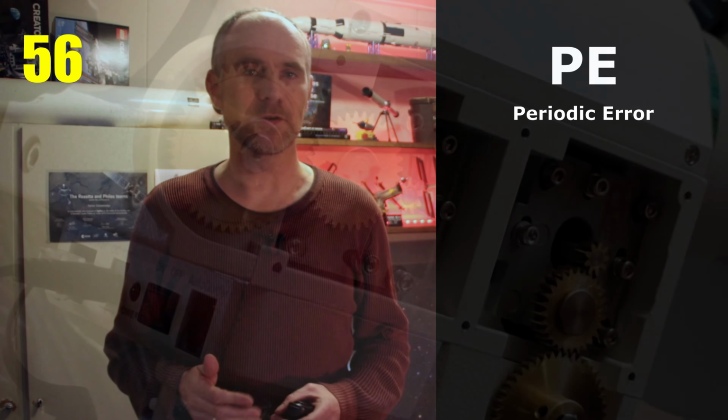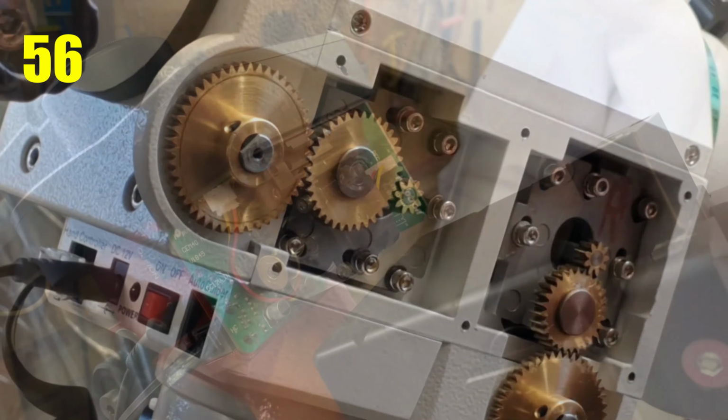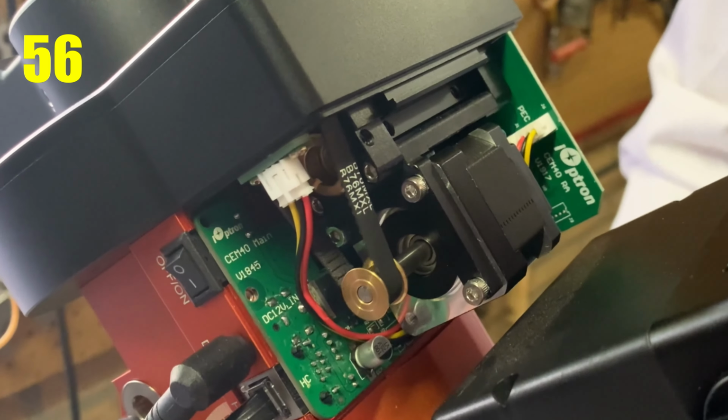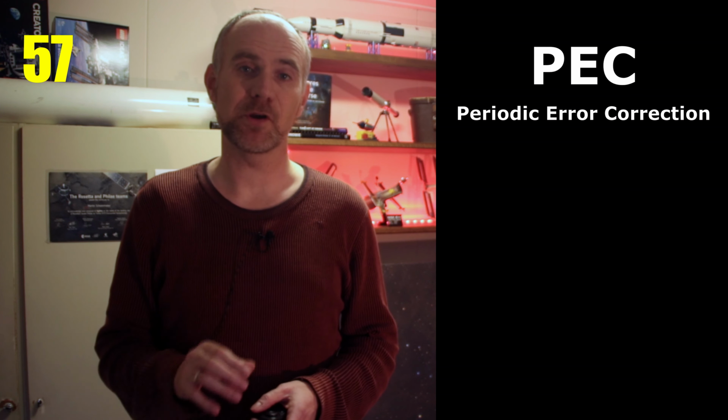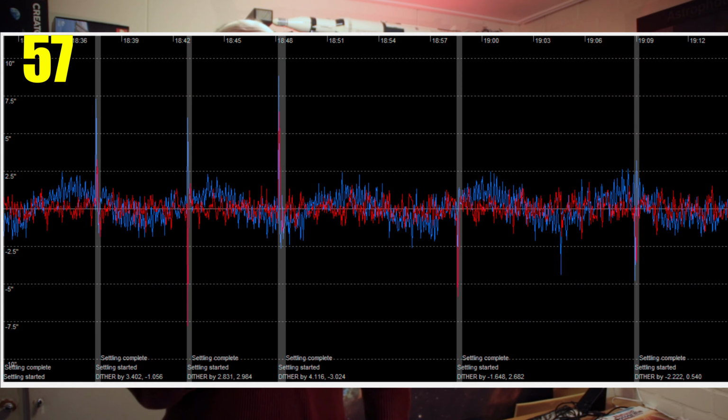Due to the way cogwheels and worm wheels are interacting with each other, inaccuracies in these wheels will reoccur on every rotation, causing a periodically returning inaccuracy. PEC is periodic error correction. The mount can be trained to learn its periodic error so it can counteract the error.